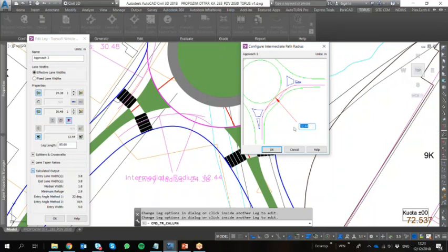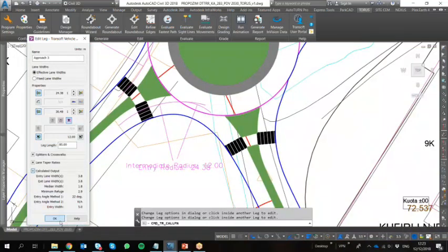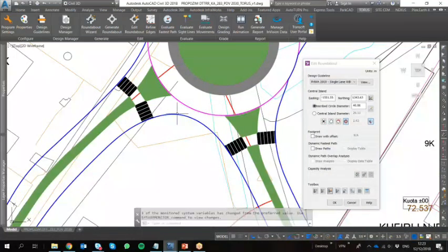And this is going to be maybe a sharp 12 meter radius. The annotations overlap a little bit, but what you see is that we now have a very nice smooth arc, allowing vehicles to perform this right turn directly.